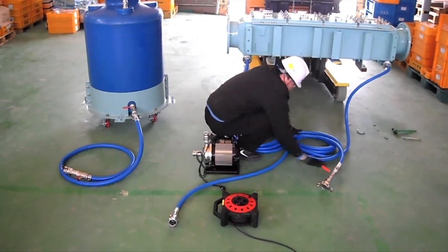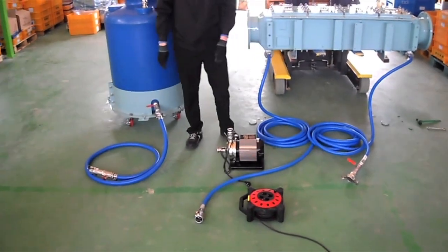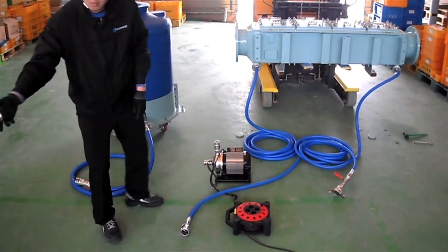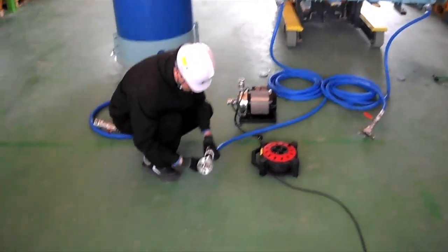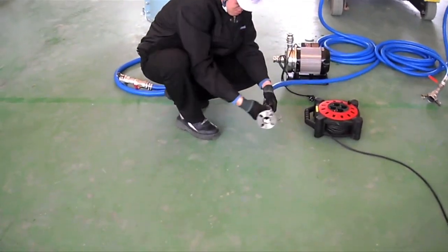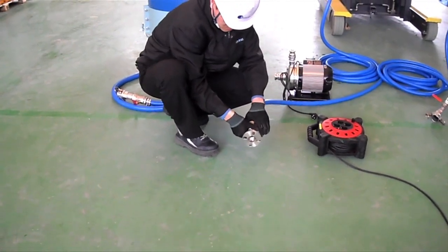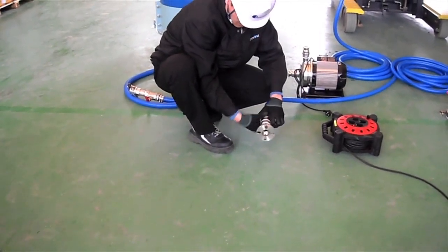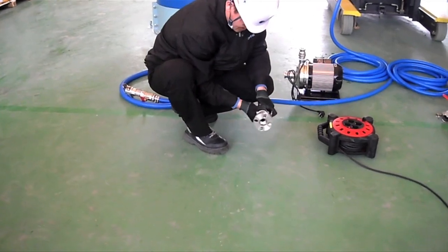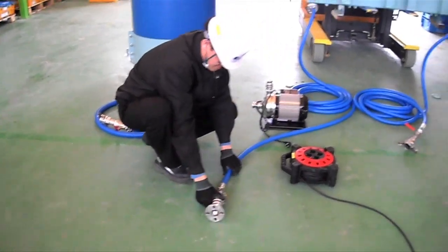3. Connect FW cooling service line of ship to coupling C4 of pipe C3 using connector. 4. Connect coupling C3 of pipe C2 to bilge holding tank pipe of ship using connector. Connector will be provided by the manufacturer.